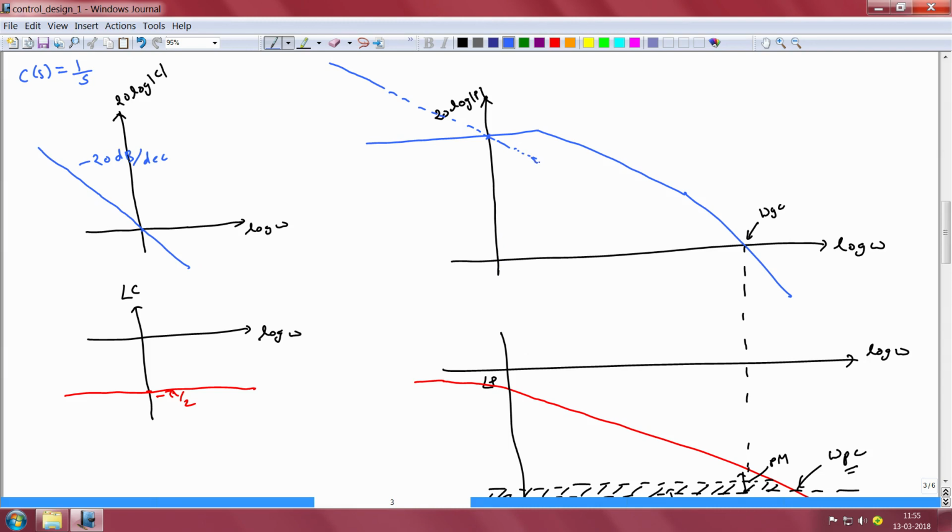Therefore, the gain of the open loop system will be less than that of the plant itself, and at the first corner frequency of the plant the roll off, the rate of decrease of gain will be increased because of the presence of the plant pole, and so on and so forth. So, the magnitude characteristic would look something like the dotted line shown on the right.